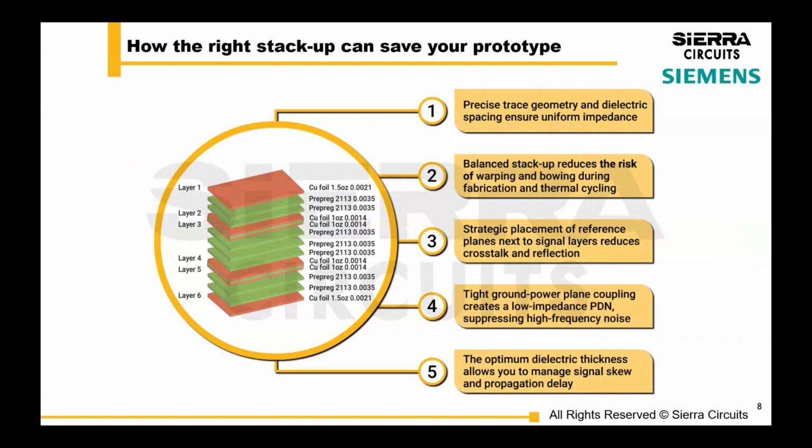So, when you're designing a stack up, and you have an idea of the HDI portion, you have an idea of the signal integrity that you want to achieve, you also have to create a mechanically good stack up, which basically means you don't want to risk warping or risk any bending or flexing during the PCB process or even in the assembly process.